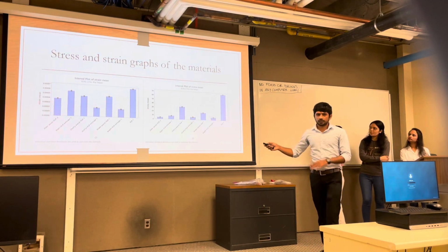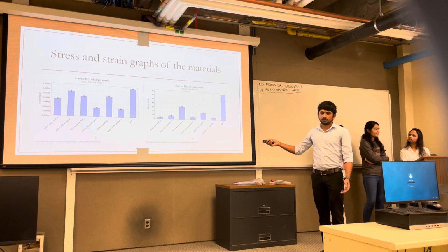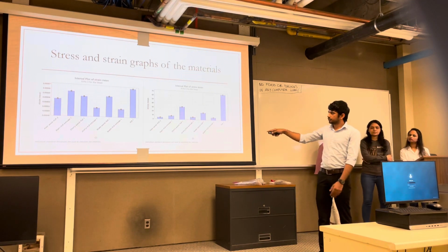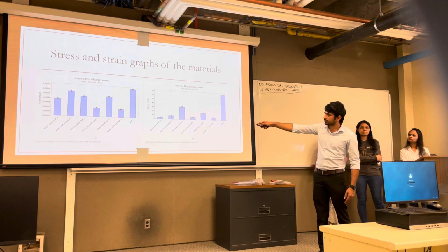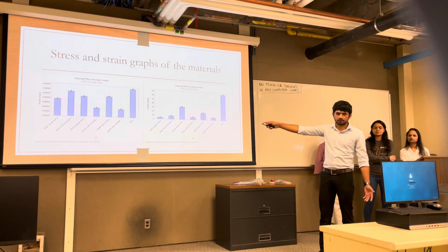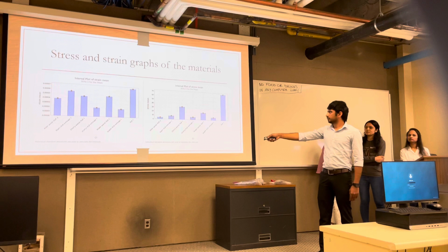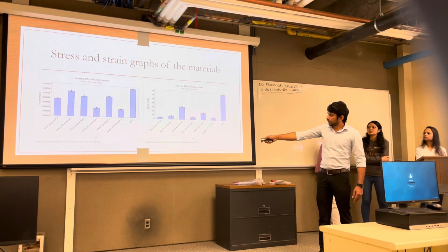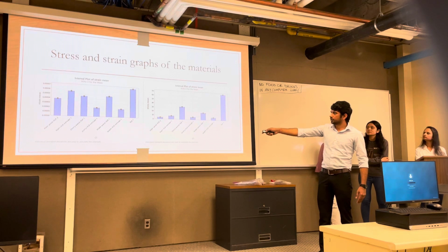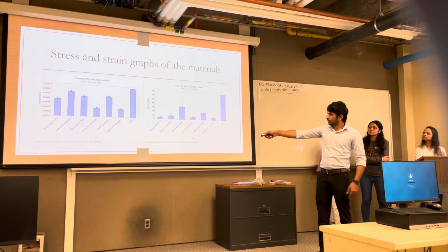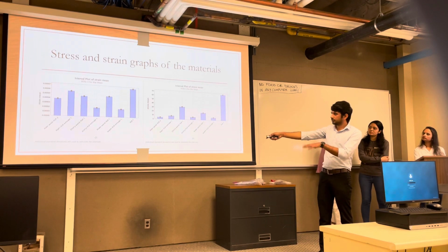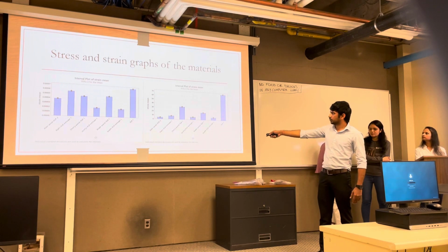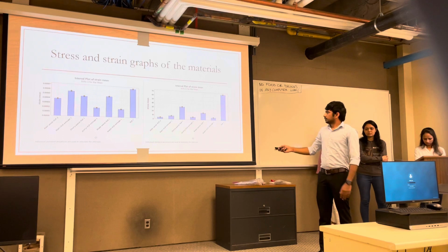We tried to make an analysis comparison, but it didn't work because the strain is very low, as can be seen, 0.407. So we just made the graph. Here also the cherry wood has the lowest strain compared to the others, and in stress also it has more stress compared to the other wood types.